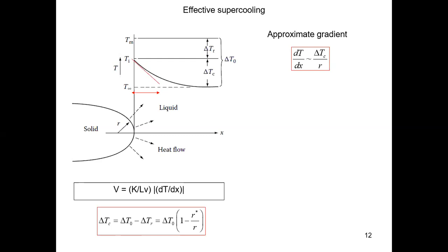But for now, we're using a common observation from diffusive transport: if this non-uniform temperature field is imposed by a finite size of this particular tip, and we're interested in the temperature gradient, then the gradient is the temperature difference divided by a certain distance over which the temperature decays from Ti to T infinity.